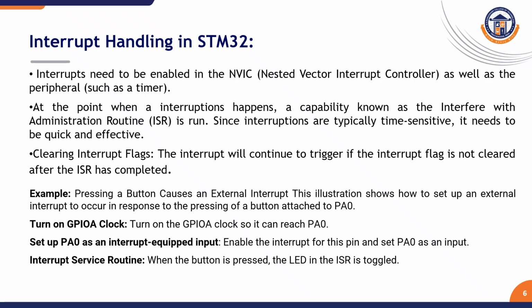Clearing the interrupt flags: once the interrupt has occurred, the flag is continuously monitored. Once we clear the flag, it comes out of the interruption. Otherwise, until the flag is cleared, the interrupt is going to keep operating. A good example for an external interrupt is pressing a button.